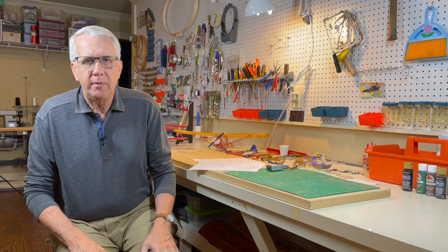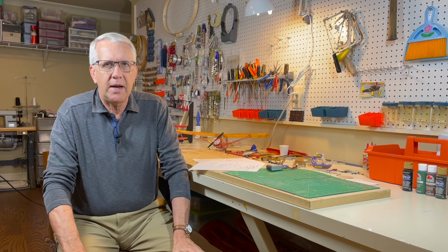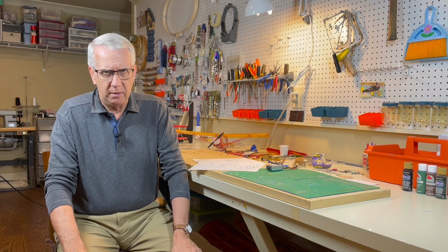So again, I'd like to thank you very much for watching, for joining me in this video discussing the center of gravity. Center of gravity is an absolute requirement for any RC model airplane. Know where the CG is based on the plans. In the quick discussion, I've shown you how to compute where the center of gravity is. Make sure that's with everything installed for flight. To include, if you have a larger model with a gas motor and a fuel tank, you should have fuel in the tank for CG purposes.